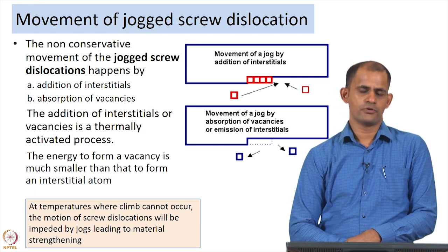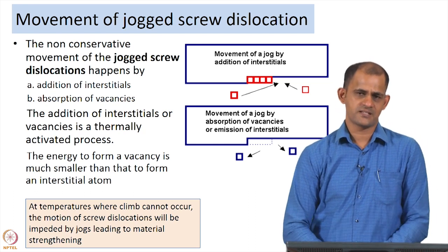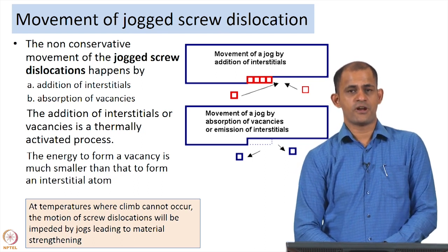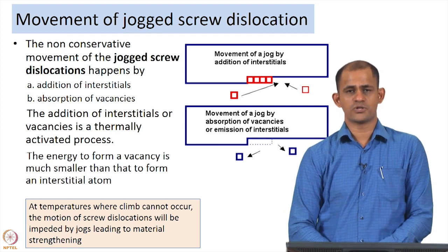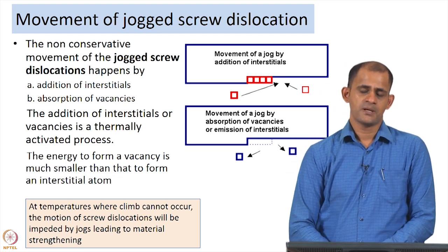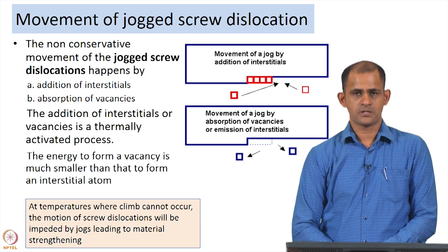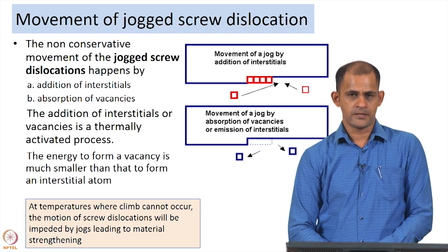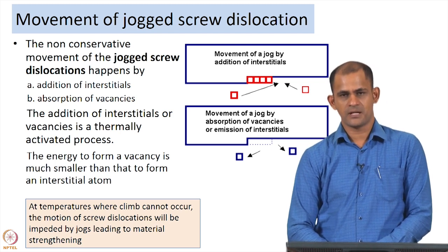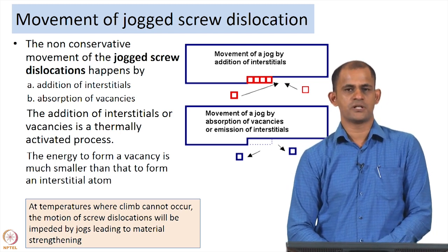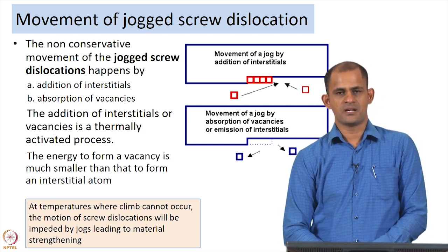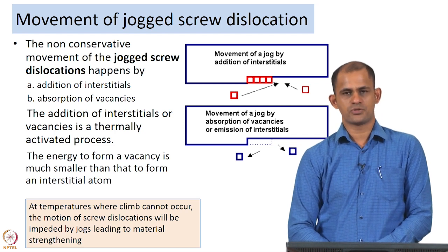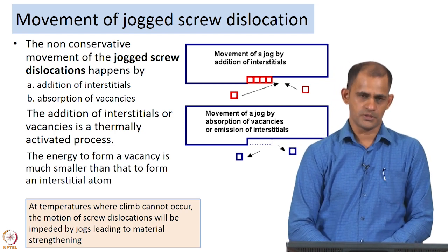dislocations. So, we are going to talk about the kind of forces that exist between dislocations, the energy of a dislocation, and the strain rate of deformation produced by the motion of a dislocation and things like that. Again this is all important because it will help us in gathering understanding in depth of the creep behavior of a material, because like I mentioned in the beginning, creep behavior involves the motion of defects, and dislocation is an important defect that contributes towards plastic deformation or creep deformation.